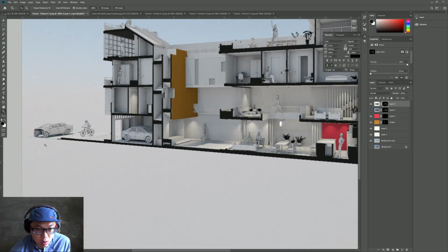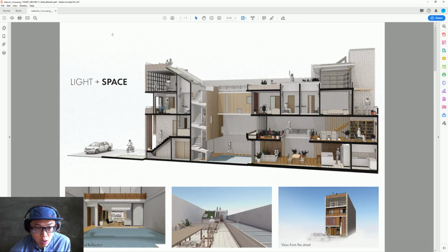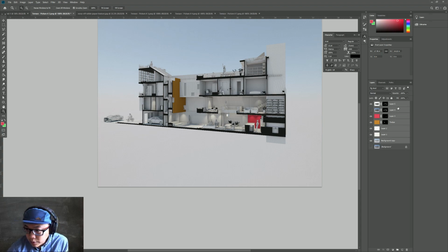And let's go back to main image. Oh, if you don't want the background, you can just create a mask as well. So I would select everything. So I press the top one, press shift, click the bottom one, so everything's going to be selected.